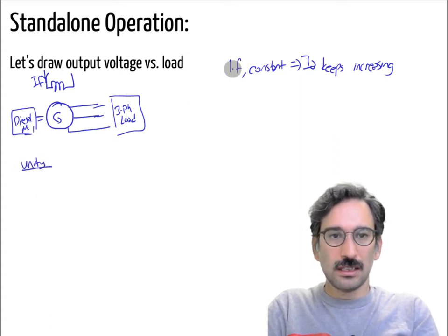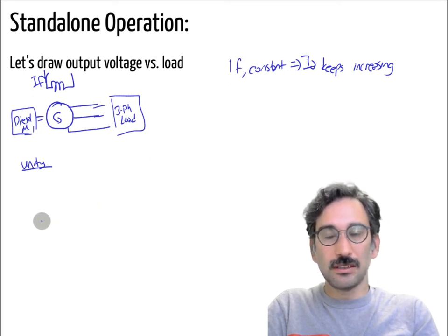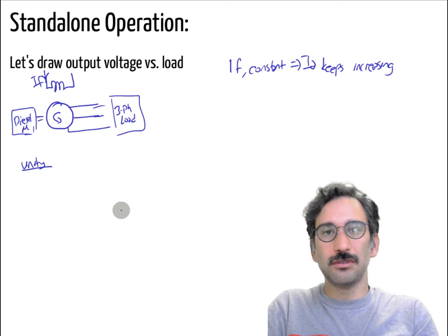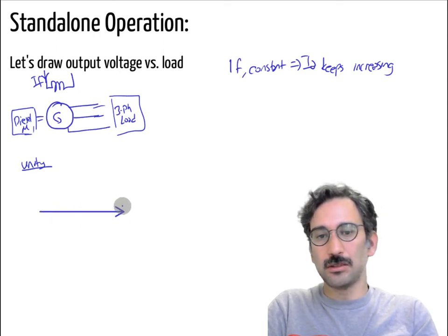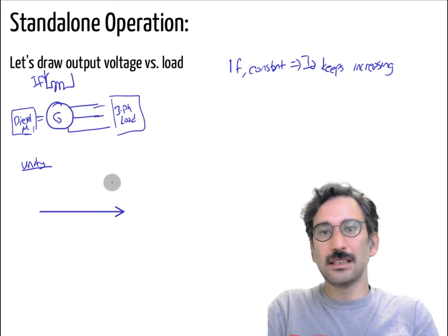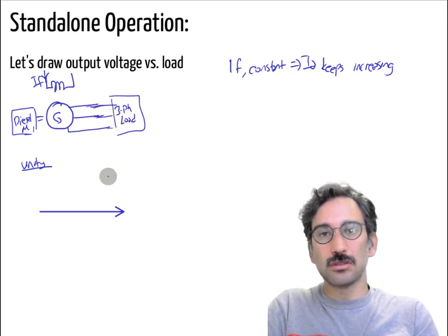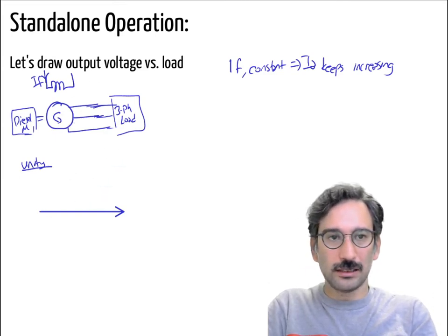So if the field current is constant, this is different from grid connected synchronous machines. In the grid connected synchronous machines I can just draw the VT and that will be a constant magnitude, right? The VT will not change in a grid connected system, but not in a standalone operation like that one, because there's nothing that holds the VT constant as in parallel connected machines.